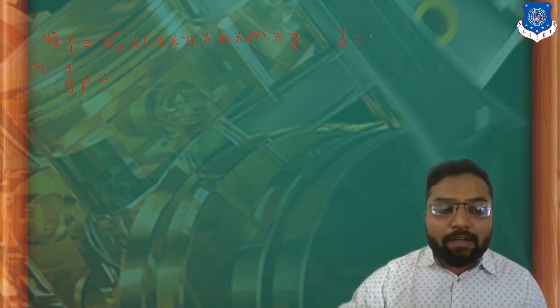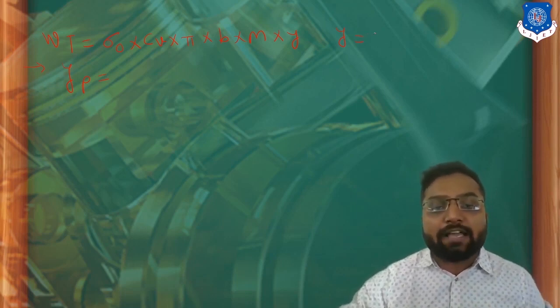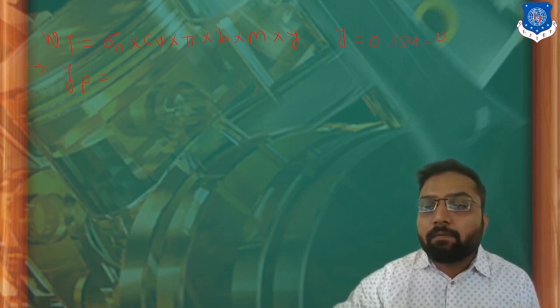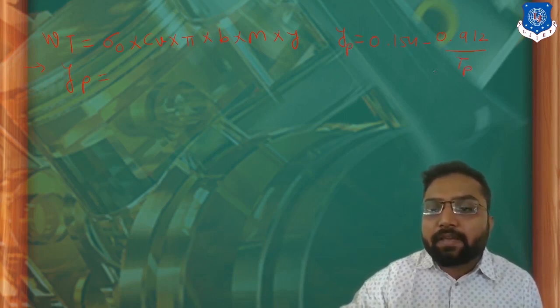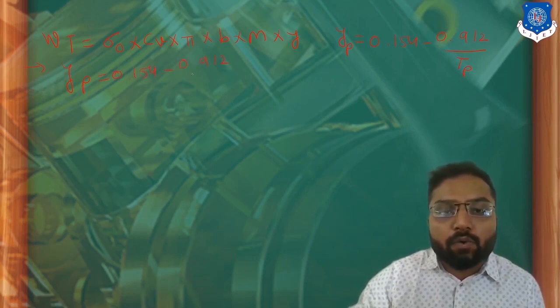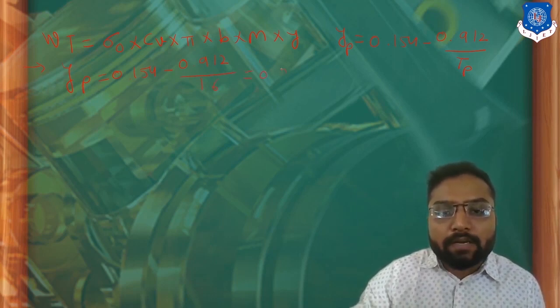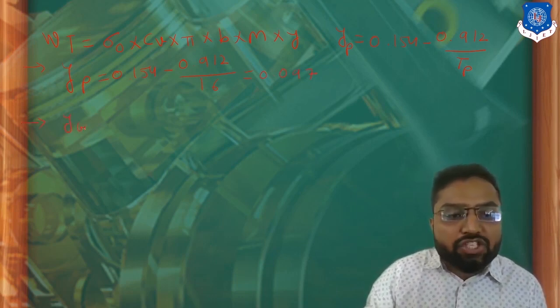For this 20 degree stub gear angle, the value of y is 0.154 minus 0.912 divided by t. In the case of YP, it is TP. So 0.154 minus 0.912 divided by 60. So this value is going to be 0.097.